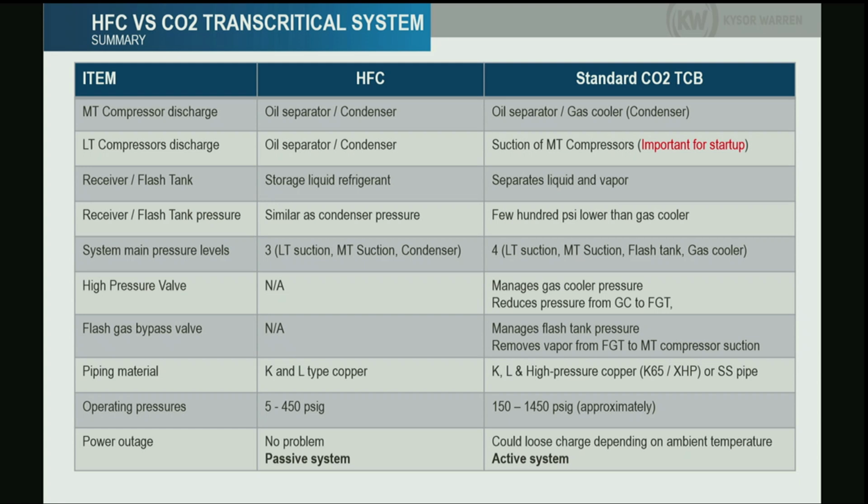That is one of the main complaints that we have heard about CO2. If they lose power, they start losing the refrigerant. If the end user, or the store, loses the refrigerant, you lose your capacity of cooling your product, right? So that is the main issue that we have with CO2 right now. There are some solutions for that, and I will talk about those here.